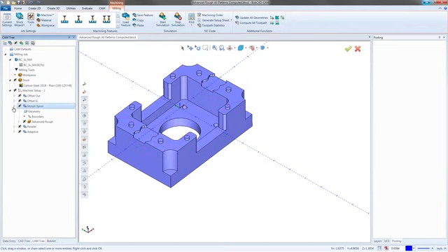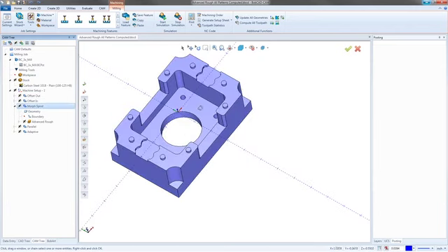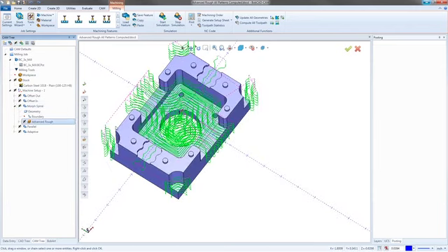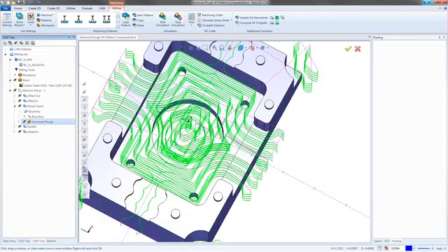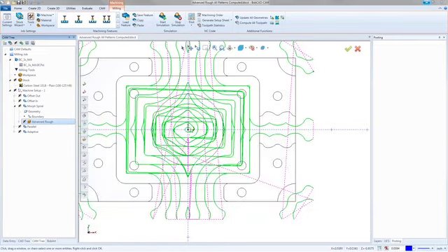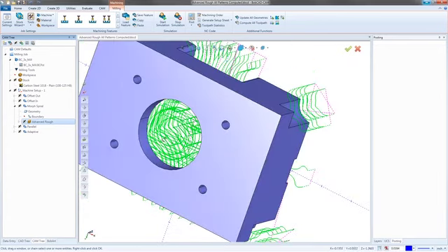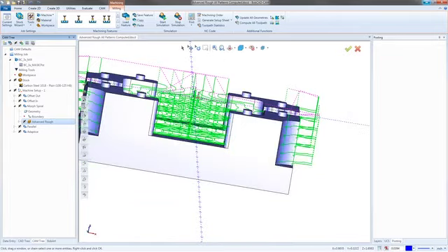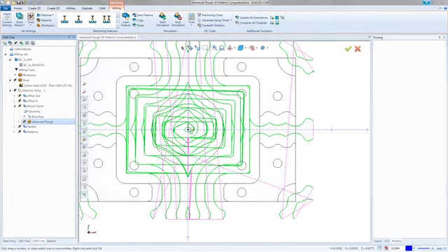The next one's the morph spiral. I mentioned it. It's tough to see what's going on with this toolpath, but it's a very cool toolpath. So if I look straight down on it, we can probably see it best. But here is the spiral, not the spiral that we see down here. That's in the bottom of this hole here, but it's just at the top. So let me go back to the top. Here is that spiral. So it's converting that kind of weird shape that we got to be able to match this rectangle, but also that open area. So it's able to work its way there.